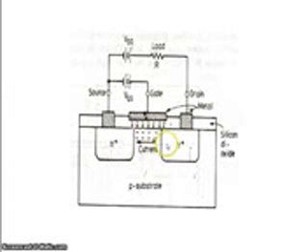Hence, these negative charges, called electrons, form an N channel between the two N+ regions. So this portion becomes an N channel. Hence, there is continuity in these N regions. So there are two N+ regions, and in between, the P region of the MOSFET has now become an N channel.